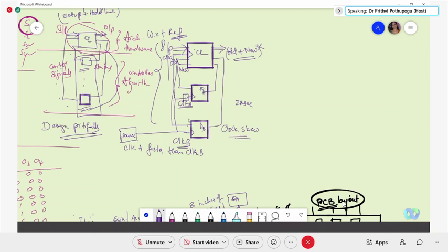And not only that, another remedy you might suggest is putting a positive edge trigger on one and a negative edge trigger on the other. That is also a bad practice. Never use different edge triggered clocks in the same design. We need to take either positive edge triggered or negative edge triggered, and don't try to use another delay element in the path of the line which is faster compared to the other line.